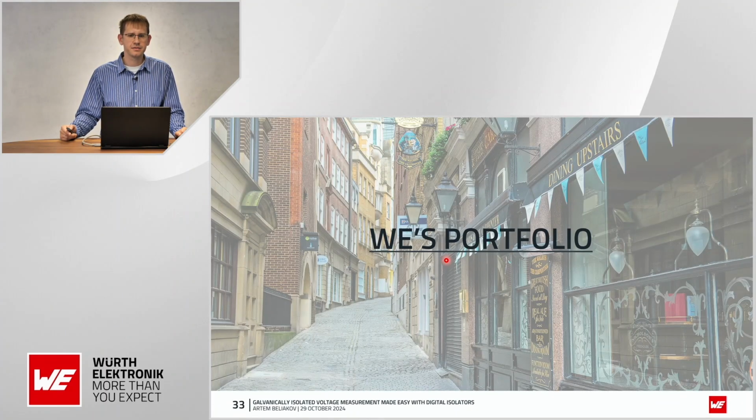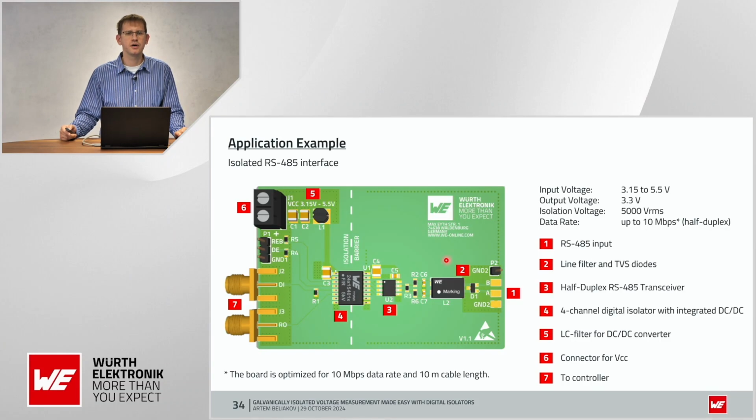Now my last part. Let's speak about the Würth Elektronik portfolio, but first I would like to introduce you our new board. The work is still in progress, but it will be a board based on an isolated RS485 interface. You can see this board on the slide. And this board is optimized for 10 megabit per second data rate and 10 meters cable length.